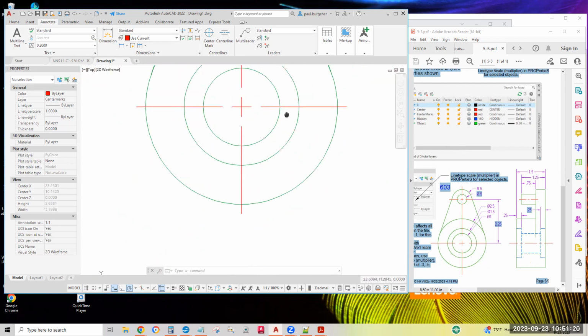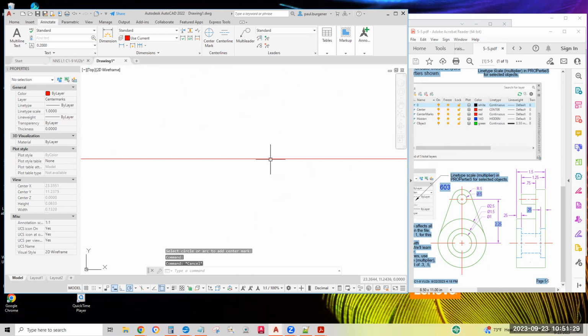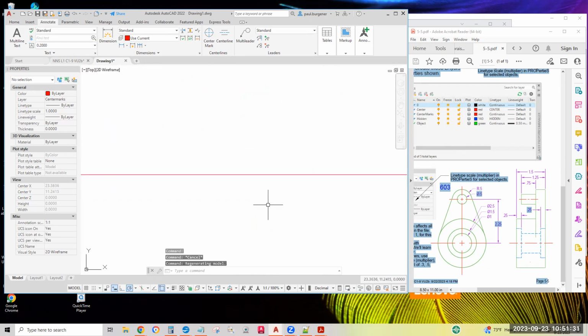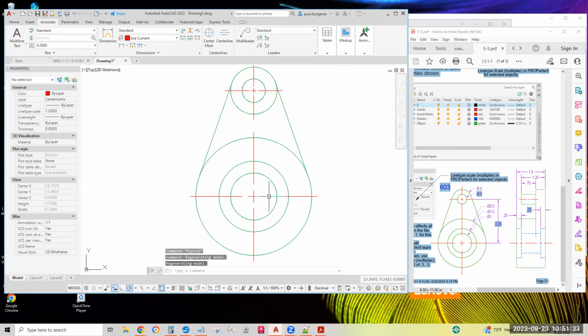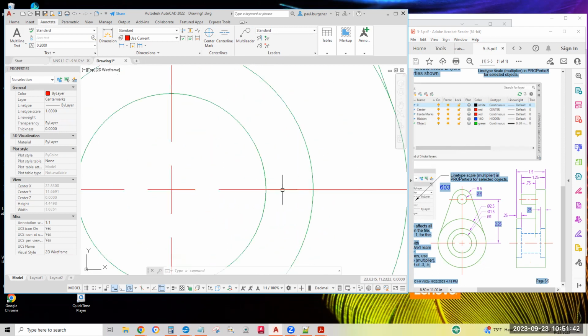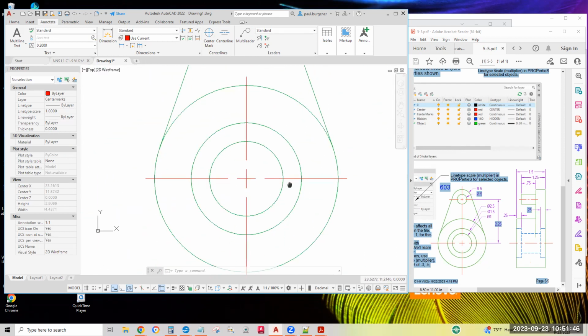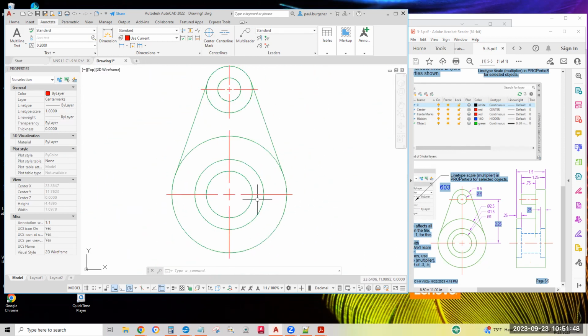Interesting that line type is not center to. Okay, the line type is center to, but you don't see the gaps anywhere. So I would say it's not necessary to change the line type of these center marks to continuous. If you zoom in and you see gaps, which might be your company standard,